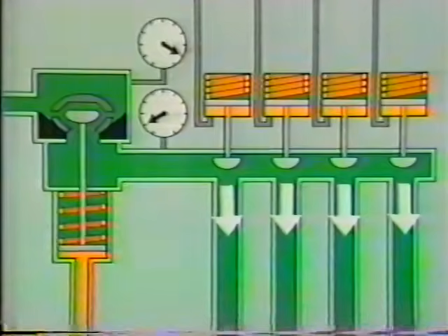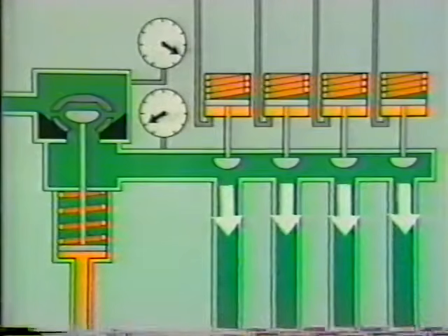This arrangement allows a small amount of steam to be admitted to all sections of the nozzle block, which causes the turbine to rotate. This condition is called full arc admission. Full arc admission allows the turbine to be heated evenly because steam is distributed equally to each section of the nozzle block. The turbine is kept in full arc admission until the internal bypass valve is almost fully opened.